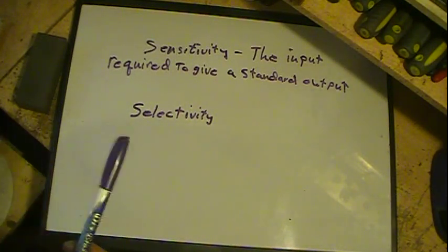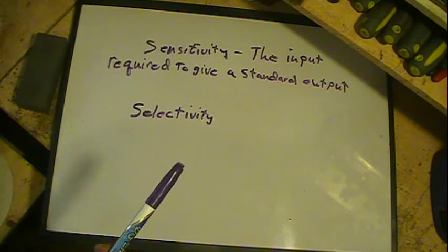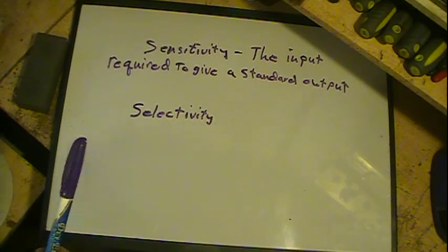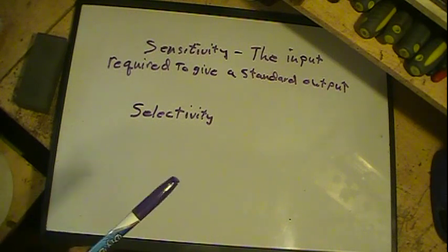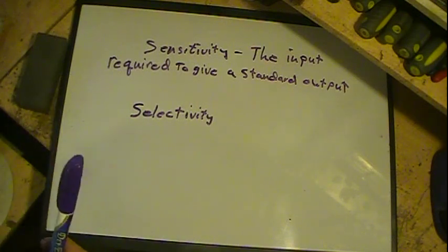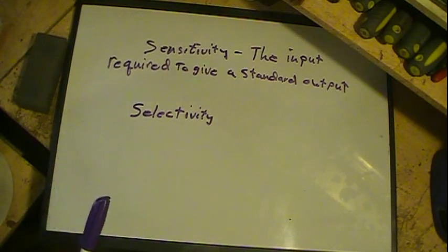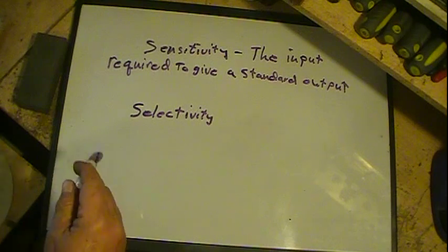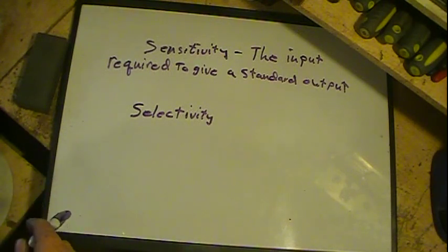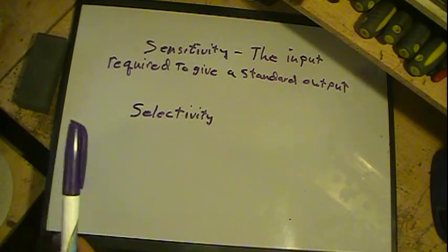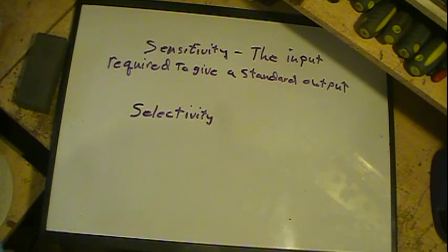If you let an amplifier run open-ended, it can introduce a lot of problems. It can actually pick up, or its circuitry can pick up, unwanted signals and then amplify those in with what you tuned in. Each section of any amplifier, each stage of a radio, all that circuitry, can act as an antenna, because tubes are high impedance, so it doesn't take much to get a signal into a tube.